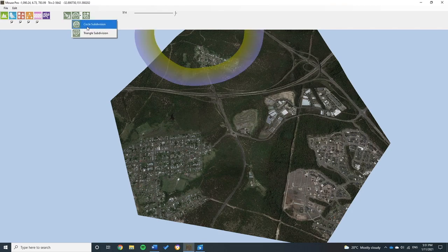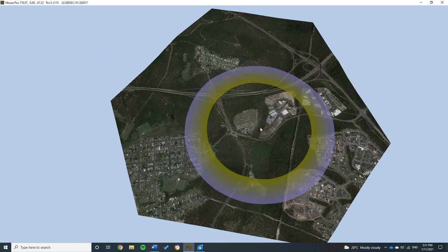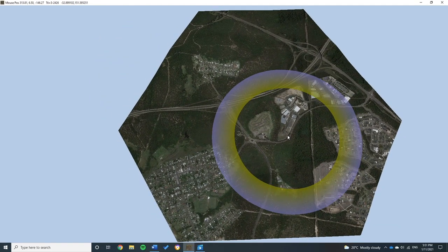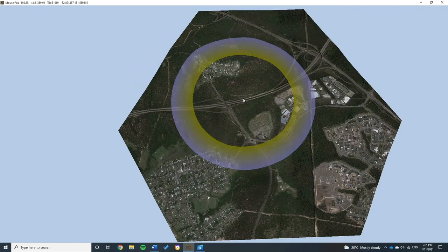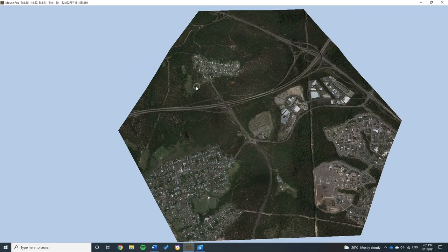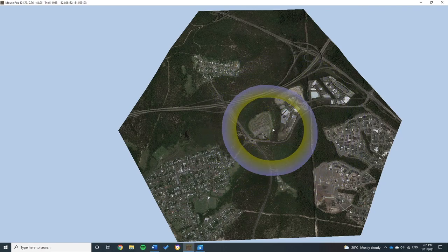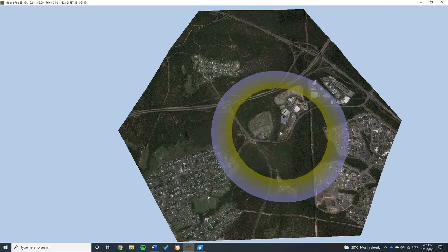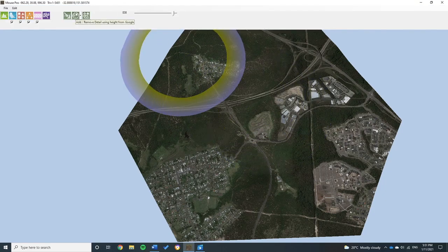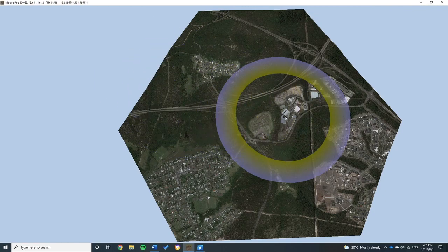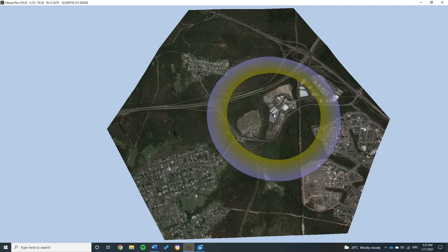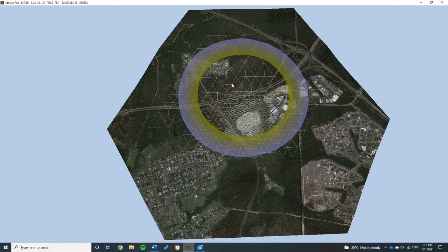Alright, so once that's done, then you want to go onto your mesh refinement and your circle subdivision. Another control I didn't mention is this circle tool that's on the screen. If you hold Control and move your mouse from left to right, you can make it a small circle or a big circle. The bigger the circle, the bigger our subdivision tool, the smaller it is. So if we press W to get our wireframe up,